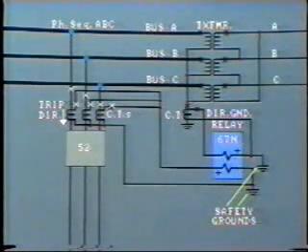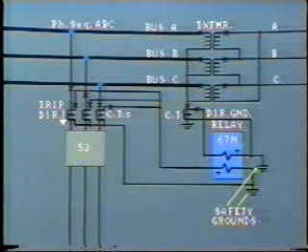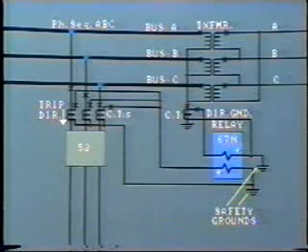Note the polarity of the CTs is clearly marked on the schematic. In this particular scheme, the polarizing quantity is obtained from the main transformer neutral, so this is current polarization, not voltage. Again, the correct polarity for the neutral CT is marked on the schematic. The correct polarity is also marked on the relay. So let's see how this works.